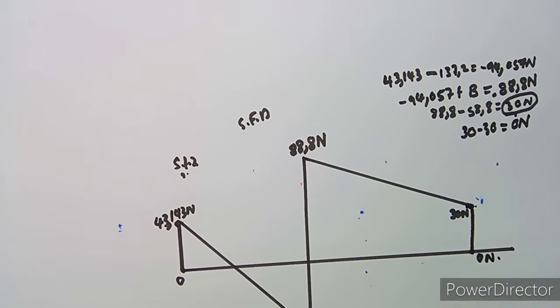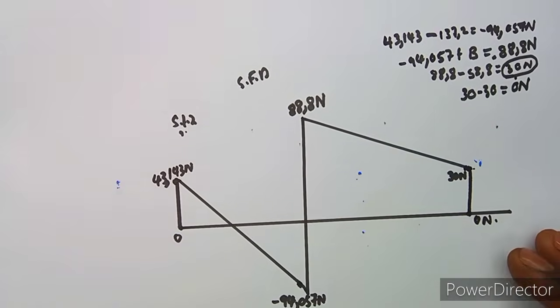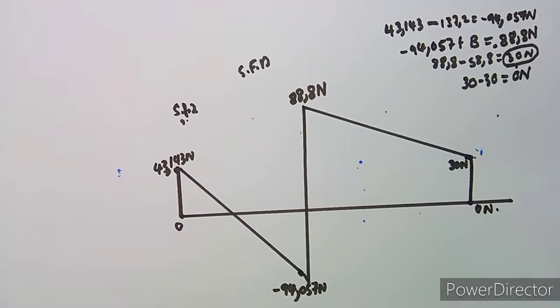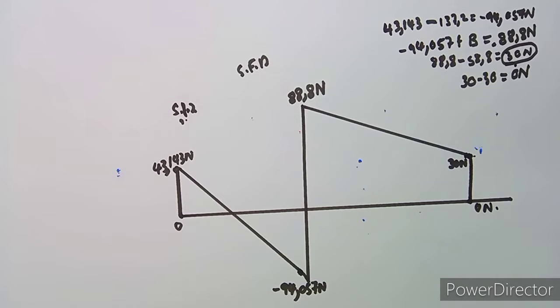So as you can see, that is how your diagram is going to look. So this is it, guys, from this, that was 5.12, which is your shear force diagram. Like I said, it is supposed to correspond these points and so forth. And take note about the point where the distributed load crosses the horizontal line, which is a very, very important point, which is going to affect us when you are now dealing with bending moments. I think I referred to this in so many classes, so we're just going to see if it is going to affect us on this platform. Okay, so that was it.